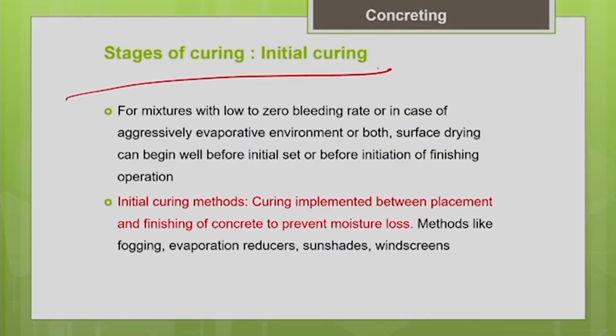For such mixes, obviously, before finishing of the concrete, I cannot apply water as my curing method. I cannot supply water for curing, because supplying water as curing will itself damage your concrete. Before the concrete attains its final set, if you try to supply water to concrete for curing, that will damage your concrete. That is why we need some other form of curing, that is called initial curing.